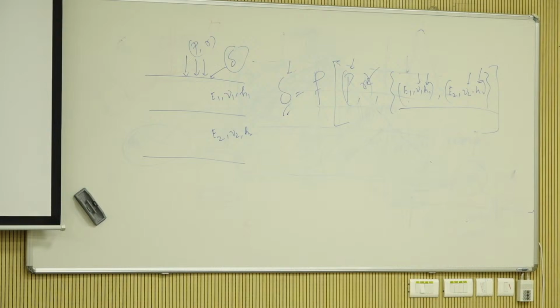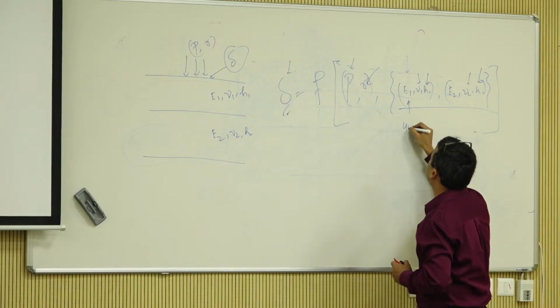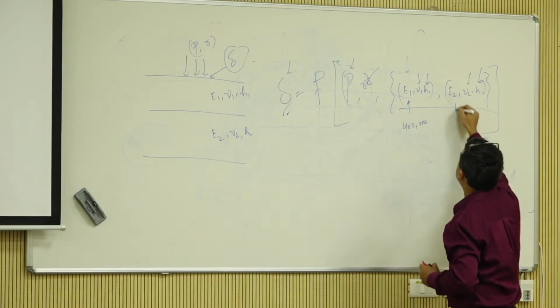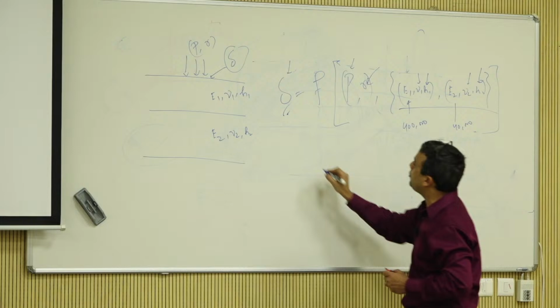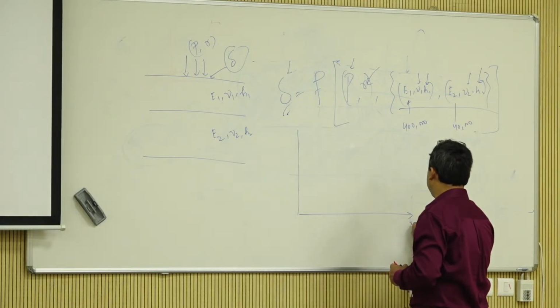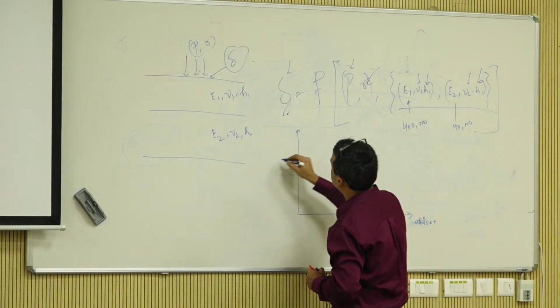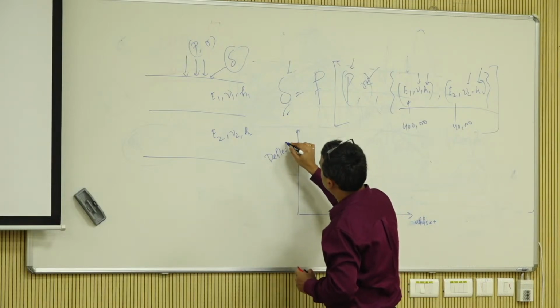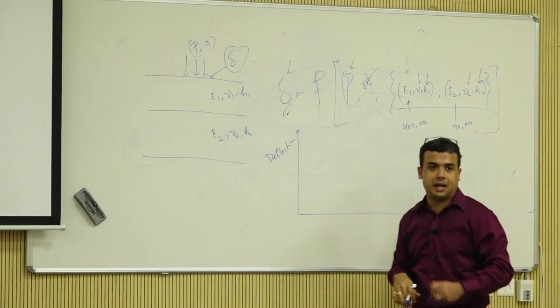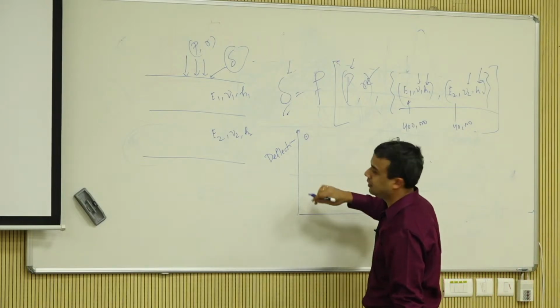How would you back calculate? What you usually would do is, let's assume E1 is say 400,000 psi and E2 is say 40,000 psi, and I am going to plot, this is going to be distance, so radial distance or offset, I'm going to call it offset, and I'm going to call this deflection. Okay, at radial offset 0, deflection is going to be very high, right?